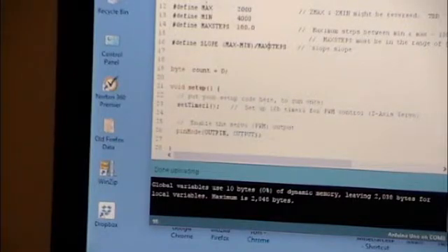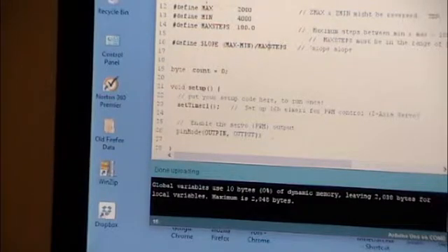One servo is enough to make him get pretty warm. These little servos are dirt cheap. These are $5. Maybe, in fact, they might only be $1.50. These draw 1/4 of an amp, which is half of what USB says you can have. So I'm drawing half my USB right here on this guy, for this little bitty guy right here. So be warned. He's not even doing that much. So if I do one, I can do this just fine.